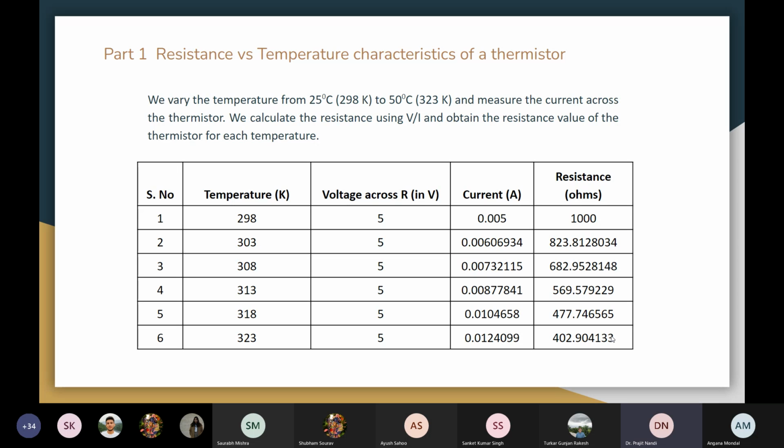Please ensure that going ahead, if you are analyzing circuits, it's not just about the voltage behavior, but also the current behavior. Another thing, in the same context: when you are powering up the circuit, it's very important to look at powering up and powering down both. It's very important to look at the current or the power consumed by the chip or by the system, because typically problems happen when you power up the supply, and that's when things are not very well defined. So when we talk of an amplifier, we say the devices inside the amplifier must be in saturation so that the amplifier behaves linearly, and so on.